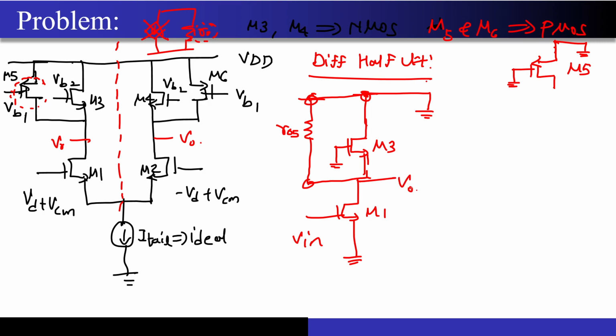Correct. Now we will see what is the GM of the circuit. So first, if I look at what is the GM, entire VGS has been applied. Entire Vin is getting dropped across the gate to source of this particular MOSFET. Correct. So the GM is nothing but GM1. There is no degeneration present. Correct. Now if I write the R out, again I will divide it like Z up parallel Z down.